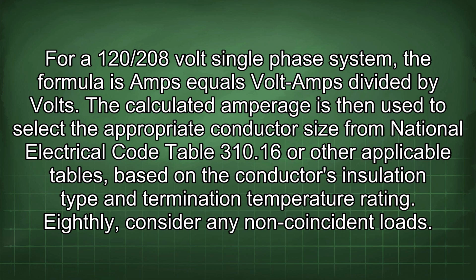The calculated amperage is then used to select the appropriate conductor size from National Electrical Code Table 310.16 or other applicable tables based on the conductor's insulation type and termination temperature rating.